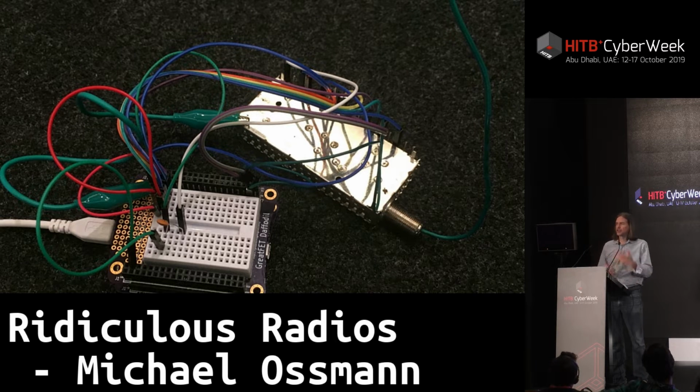It's just the analog circuitry required to take a radio signal and pull the television signal out of it, but it doesn't actually interpret that television signal. It just shifts that, cleans it up and amplifies it and shifts it down into a lower frequency range that then could be sampled by something like an analog to digital converter.